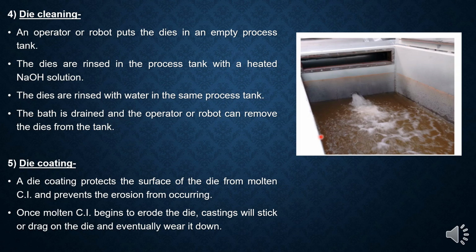First of all, in this tank, heated NaOH solution is being filled and in which the die is being rinsed and it is being cleaned. After that, this NaOH solution is being removed from the tank and water is being filled in this tank and the die is again rinsed in the water and all the bath is drained out from the outlet and the die is cleaned.